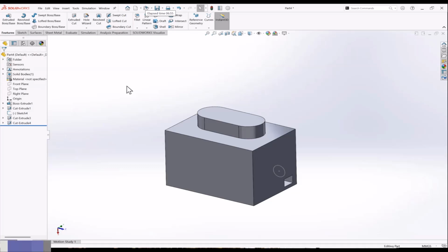So the next tool we'll take is revolve base. When we use the revolve base tool, we have to define something about the axis, meaning I need to define one axis of revolution and one profile to revolve around that axis. So what I'll do, I'll just create some random axis and then we have to define the profile, what we have to design along the axis.